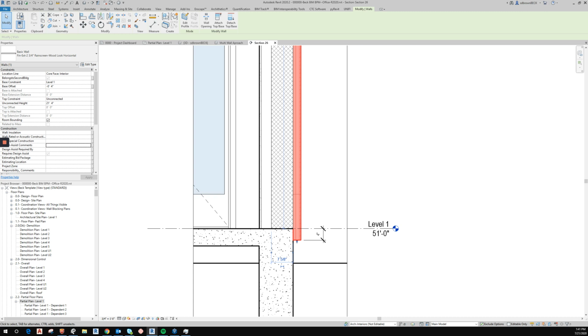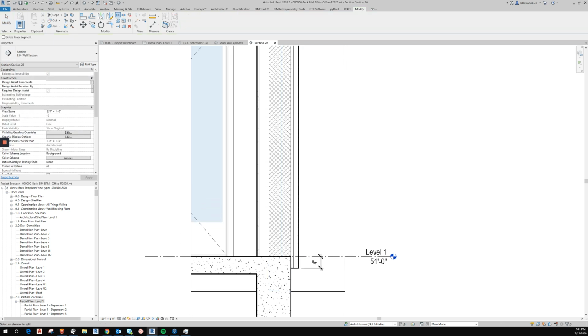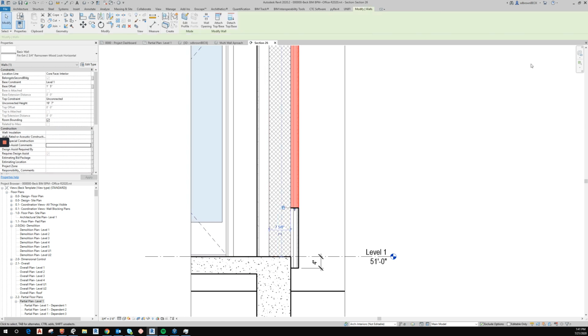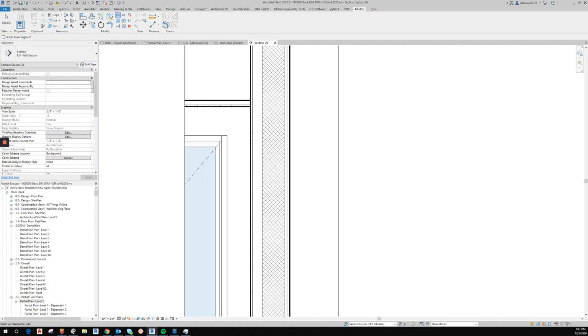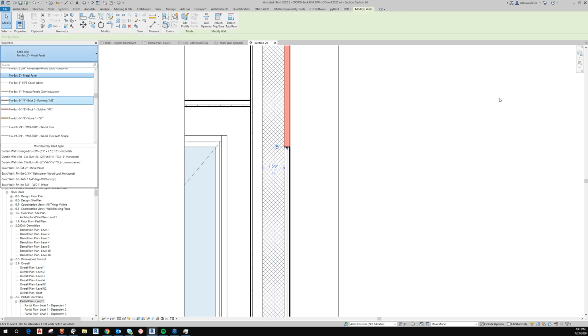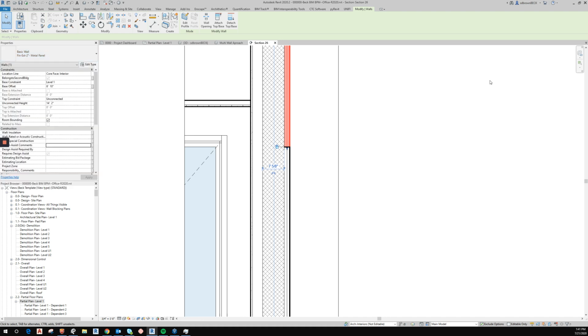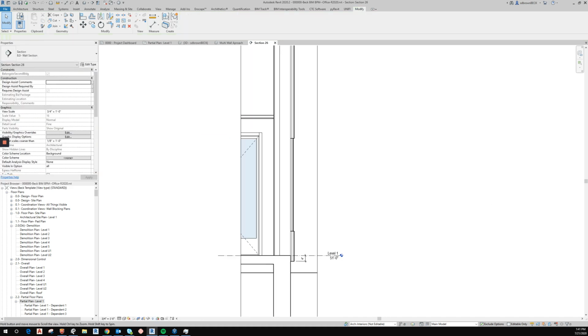You also then have the flexibility in section to split the wall. So you can use the split tool that's under Modify, and this guy up here, and very easily split the finish of the wall and change a portion of it. You know, if that was metal panel, we can change it to that. So it allows, and we can stretch it, split it again. Up here we can go back to our rain screen or EIFS or whatever it is we might have different finishes for.